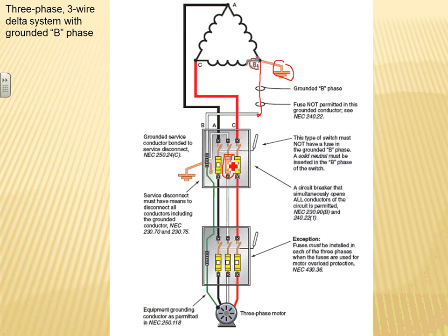The grounding system. So I thought, just to, this is at the main. Now if you go down to the level of the overcurrent protection device for motors, which we will talk about tomorrow, if you're using one fuse as a dual function overcurrent protection device, ground fault and short circuit as well as overload, doing dual function in one device, not as a backup, which is allowed by code, then you have to fuse it.